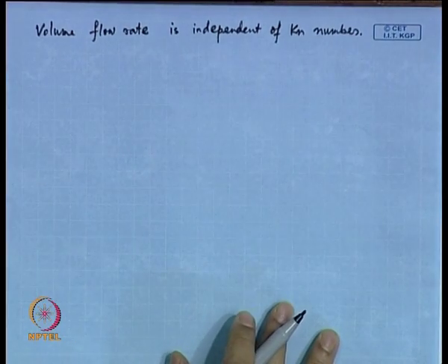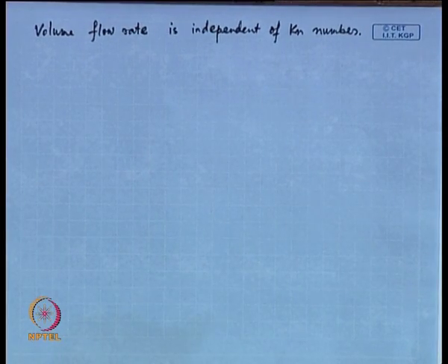This is a very important thing. From continuum flow, you found some volumetric flow rate. You have a fixed plate, a moving plate, and you found some volumetric flow rate. What this says is, even if you did all these things, first order boundary condition, etc., the volume flow rate remains the same. So whatever you had from the continuum solution was good enough, as far as the volumetric flow rate is concerned. So this is independent of Knudsen number. This is something very important you need to remember.